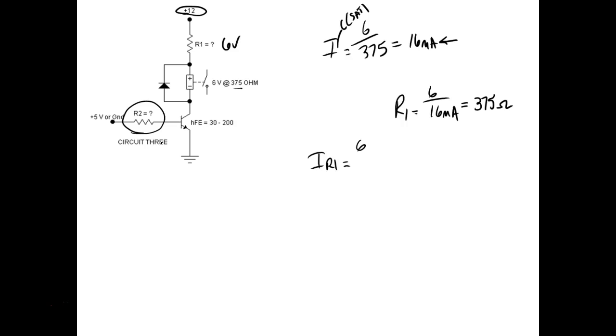So you got a relay, a DC relay. By the way, if it says it's a 6-volt relay and it's DC and you don't know the ohms, what can you do? We got an amazing meter called an ohm meter. It's DC, right? It's not AC. It's not depending on XL.